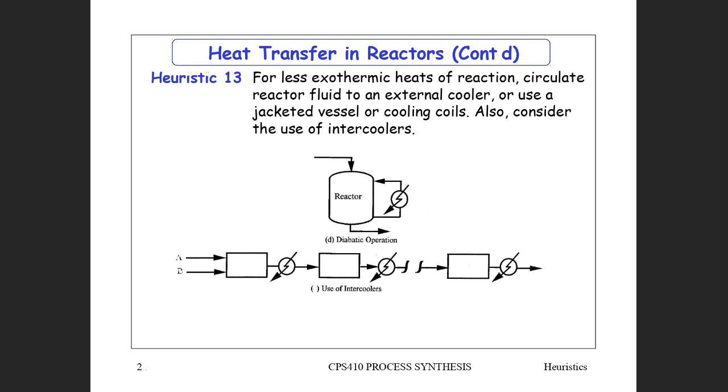So this is a bit more expensive because there are many heat exchangers, so you don't get economy of scale. Many reactors, many reactor sections. Compared to if you have a single reactor, you get some economy of scale. A single heat exchanger, you get economy of scale.